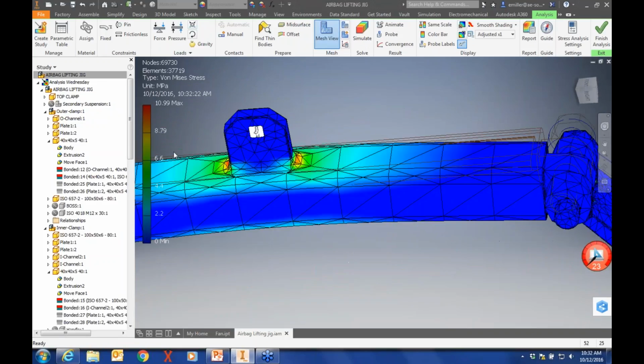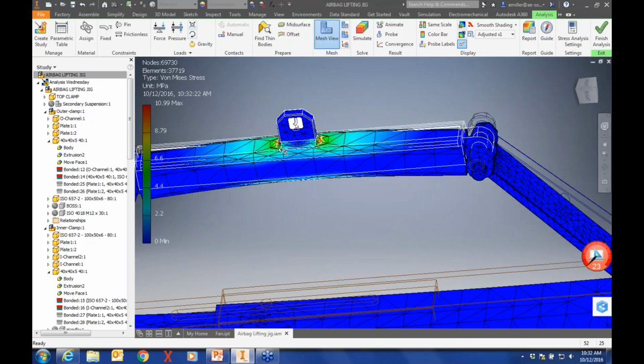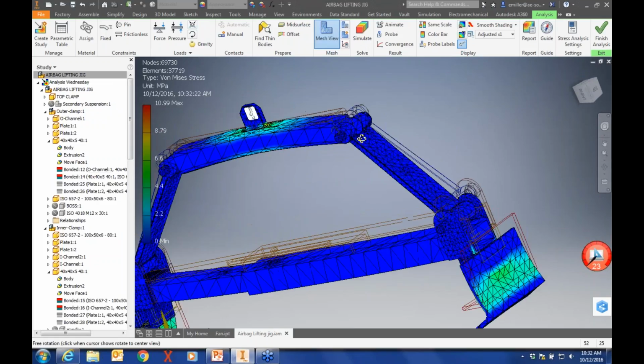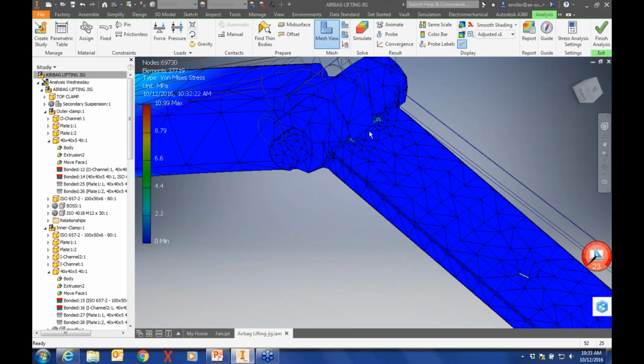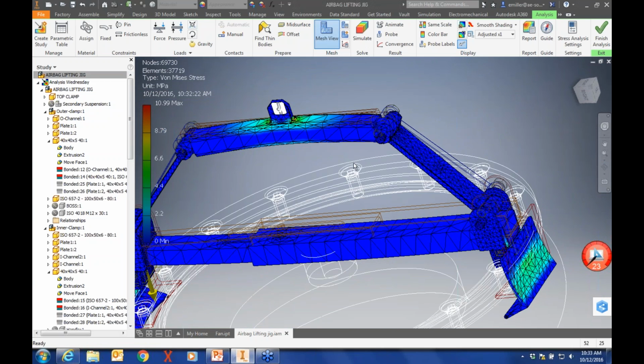But again, up on top, if we verify that our stress is highest there, and if we make a change to that, maybe the high stress is going to move to a different component, and then maybe we'd still have to be concerned about that. So we want to make sure it converges if we make any changes, and optimize the design after doing a couple of these.